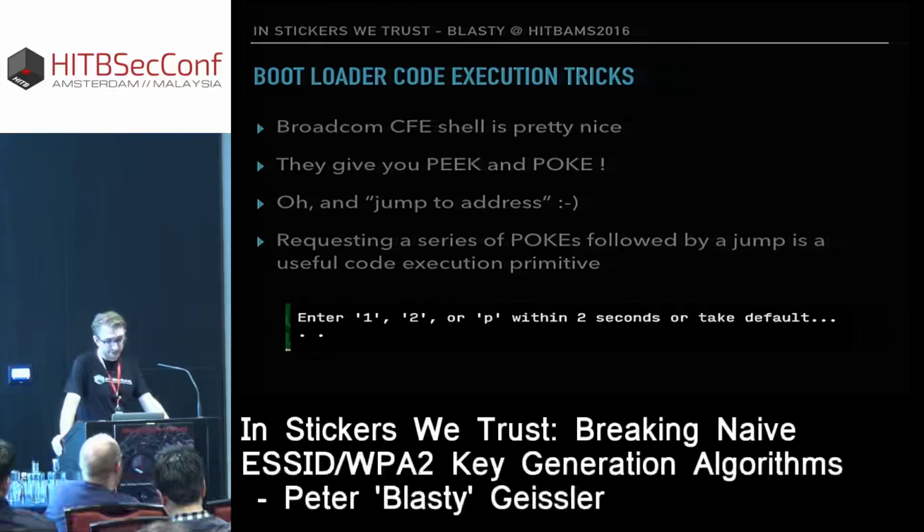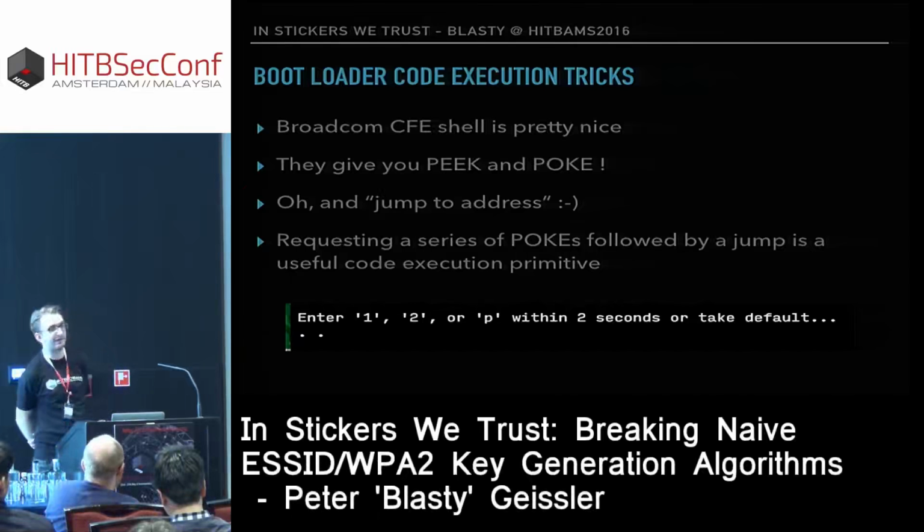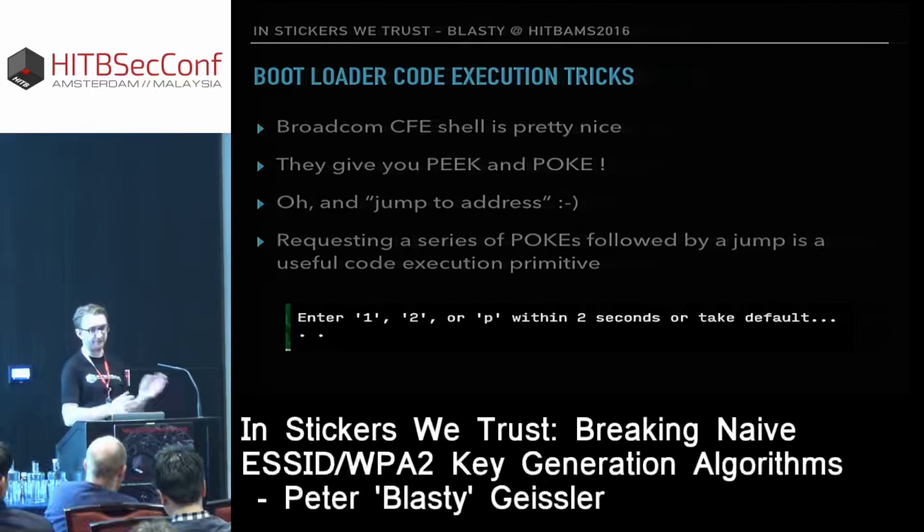It's a really nice bootloader because at the moment it starts, eventually it will give you this message which says enter 1, 2, or press P within 2 seconds. So if you press 1, it's going to boot image 1 from the NAND flash system. And if you press 2, it's going to boot image 2. So there's a recovery system where if one image gets corrupted, then it can still boot into the second image, and this is normally done automatically, but you also have the option to override this during boot.